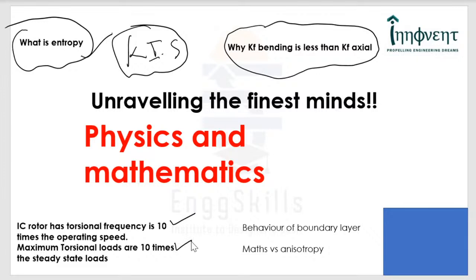There can be questions which can be very, very difficult to answer, because how exactly a boundary layer behaves when the viscosity goes down, because for no slip condition, it is the viscous forces which actually decelerate, rather become almost equal to the inertial forces, and therefore how the nature retaliates when you are reducing the viscosity. That can be a very, very involved question.